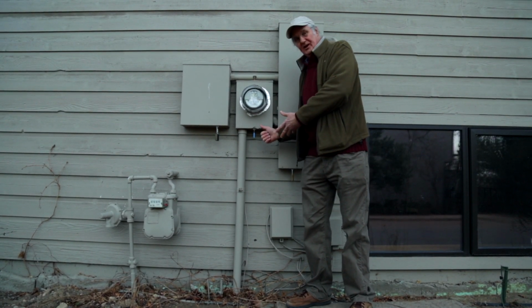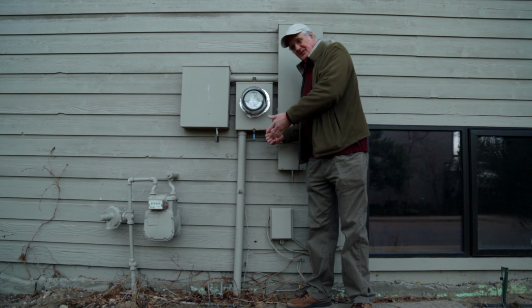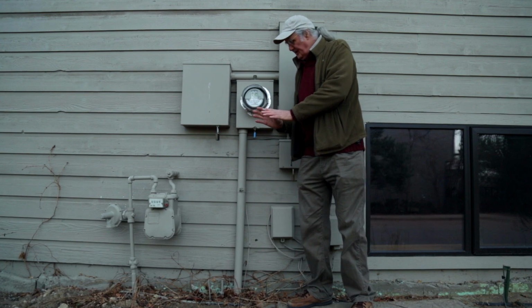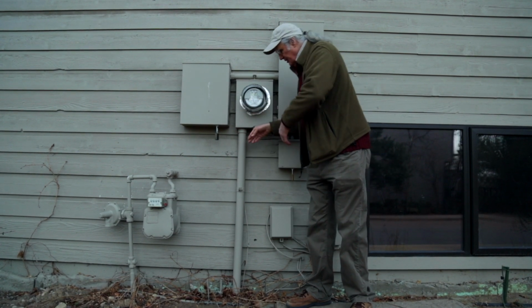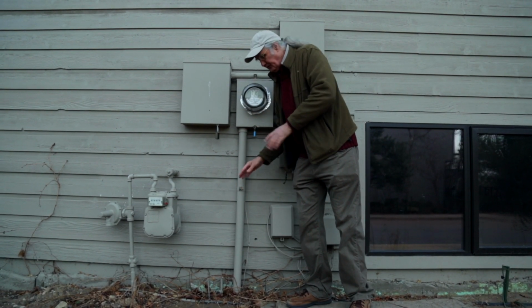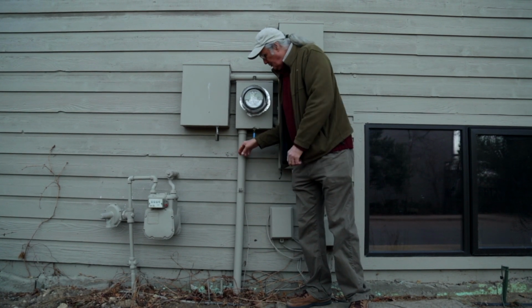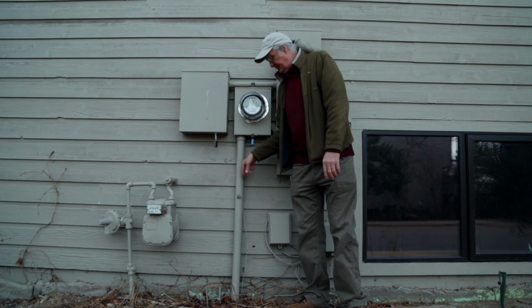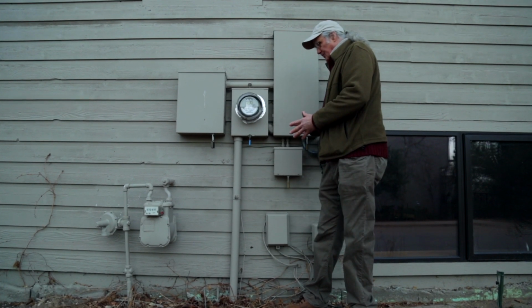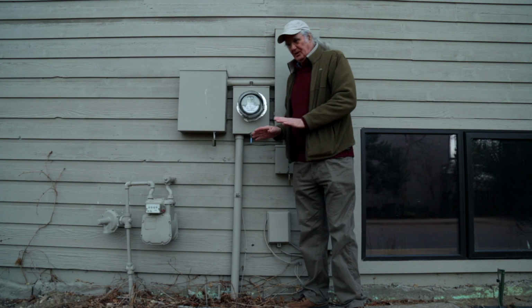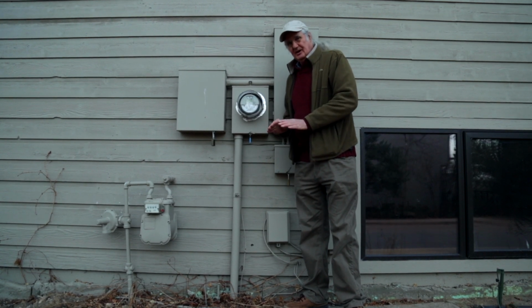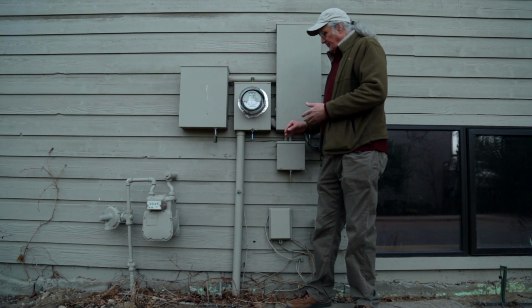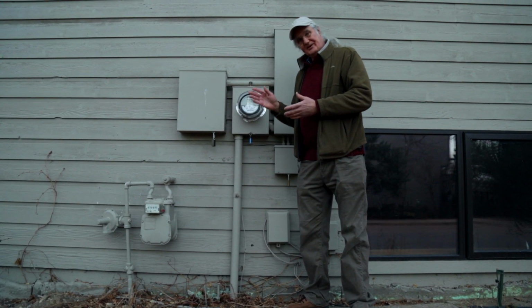The current's always what it is on the hots. It doesn't come in any other way, but it goes back on the neutral here and elsewhere. So what we teach is that we need to bring that current back here, so 100% or close to it goes back here. There's always a little bit trickling on the earth, but we want 90 plus, 95 plus percent or more, 98% on this path. So that's not a deal breaker in our book, but it is something that we need to caution the client, the homeowner, the person who's interested in buying this house, that if they have these other parallel paths, we need to find them and mitigate them.